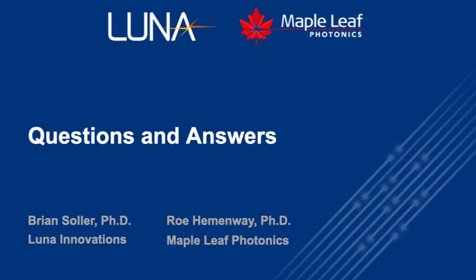Yeah, so that's a good question, and we get this a lot. You've got OFDR as a technology, then you've got OVA as a product, and OBR as a product. They're both OFDR technologies. The OVA is designed to measure strong signals and things that are transmitting or reflecting a lot of light. And it includes all of the polarization analysis, so you can use it in reflection or transmission.